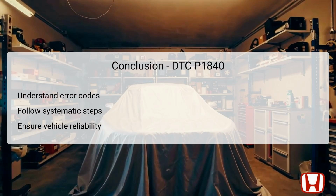In summary, understanding DTC P1840 is fundamental for diagnosing and correcting issues related to the CVT speed sensor and TCM operation in the Honda Civic 2022 Plus. By following the systematic troubleshooting steps outlined, technicians can effectively isolate the root cause of the problem, whether it be a faulty sensor, a malfunctioning TCM, or wiring issues.